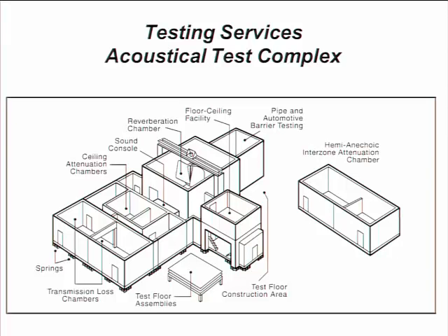The temperature and humidity are controlled. There are very specific dimensions and diffuser setups to meet the standards and have diffused sound fields. We continuously study these chambers over and over. Ours date back to 1965, and we'll have data for the last 48 years every couple months of how they perform. We're looking for consistency from test to test.